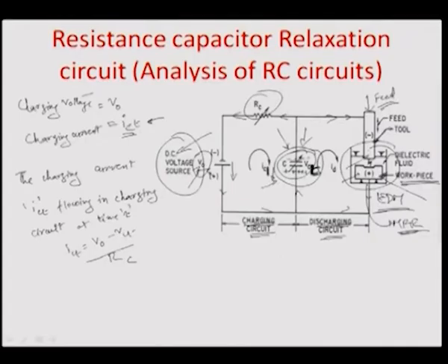If we consider the way that the capacitance charges, let us say Q(t) is the amount of charge that is coming into the capacitor. So, Q(t) can also be given by the fixed capacitance value C times Vc(t), where Vc is the voltage on the capacitor as a function of time.